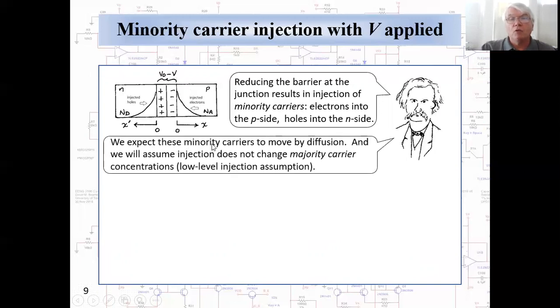We expect these minority carriers, once they're injected, to move by diffusion, and we will assume that injection does not change the majority carrier concentrations. This is what's known as the low-level injection assumption.